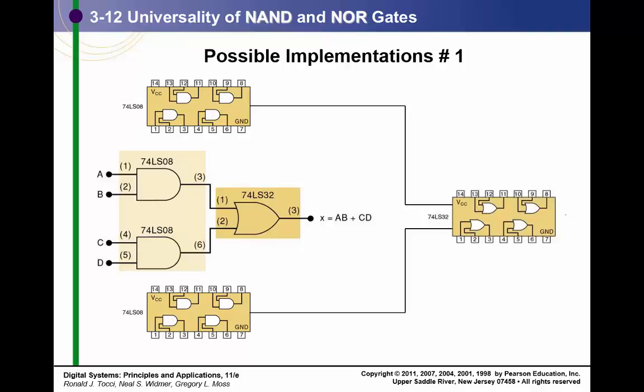Now they show this here. These 2 AND gates are on one chip, so we're using pins 1 and 2. We're using 4 and 5, this one for here. And then over here we're using 1 and 2, so we're using this chip right here. So this is the way we would wire this up. We would tie this to 5 volts.